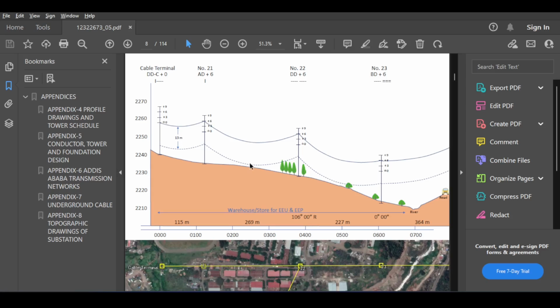Also notice in this project, the minimum clearing spacing was 13 meters. You can see that in this position, the minimum clearing distance was achieved, a 13-meter separation between the cable and anything that is close to the ground. And I've mentioned that there is a minimum distance requirement, a clearing distance between the cable and the ground. It depends on the voltage of the current that runs in the cable. Now, I'm not an electrical engineer, so the electrical engineer is who decides exactly what is happening here.